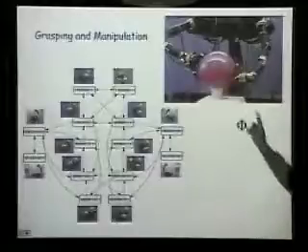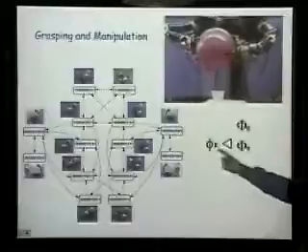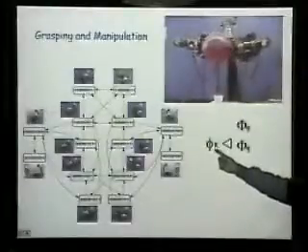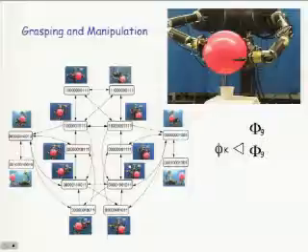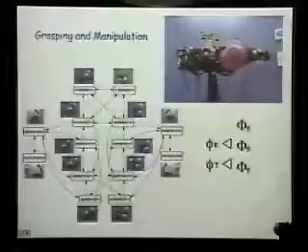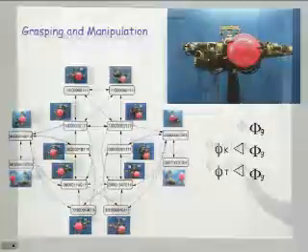Now, and when it is, it's going to run a second controller in the null space of the first one, which is to kinematically condition the arms into a place where they're more comfortable, in the middle of their workspace, more isotropic. Once it gets there, it's going to do a twist test. It says, move it way over to your left, subject to the grasp. Don't drop the grasp, right? Don't destructively interfere with the grasp. You've got to preserve it.